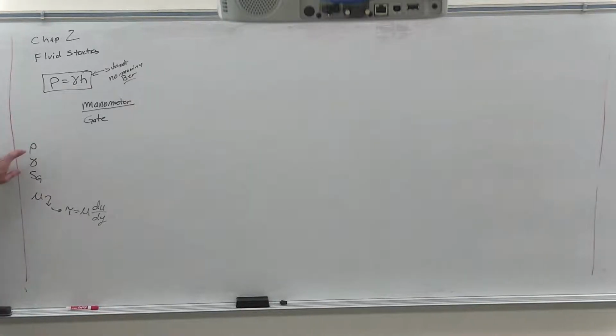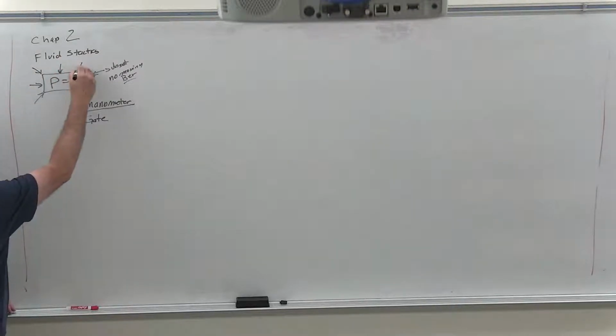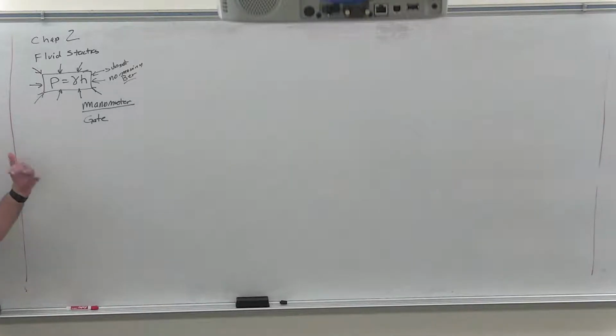So fluid properties mostly encompass this. Now there was P equals rho RT and ideal gas and some gas things, but I kind of think that's covered in thermo. So I'll just say, okay, there's a similarity, and we just go on. But this whole chapter is primarily focused on the implications of that, in that as you go down in some sort of liquid, the pressure increases because of all the stuff over your head, you know.